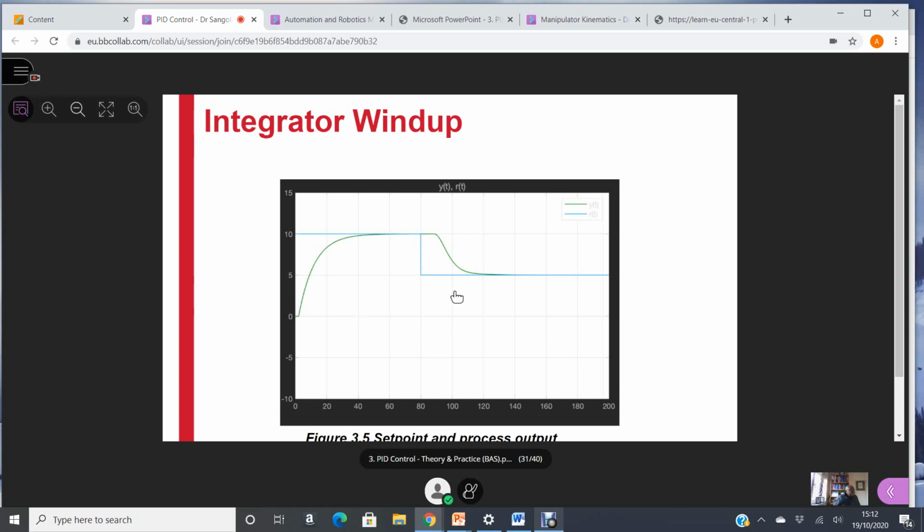The control signal will reach steady state in about 24 seconds. You see, the change in input is there, and you'll see that it takes about 24 seconds for the output to reach a steady state. But it reaches a steady state which is outside the range of the actuator. And so the actuator will be operating in a non-linear range during that period. So you will have actuator wind up.